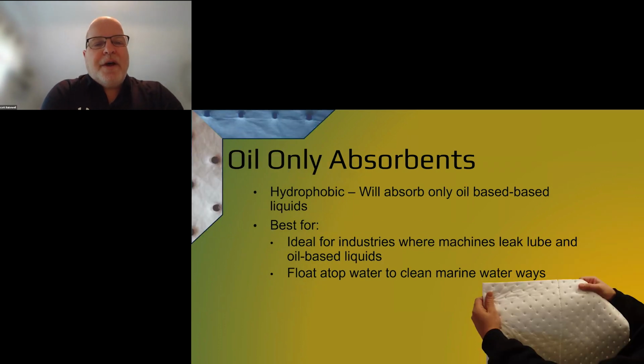Oil-only absorbents are hydrophobic. They'll absorb oil-only based fluids only, as I had mentioned earlier. They're ideal for industries where machines leak lube and oil-based liquids. That's one application. Sometimes we see them used indoors, and I kind of wonder on occasion why people are using an oil-only on the floor when solvents could be leaked at the same time, but we do see it. And keep in mind, they float.